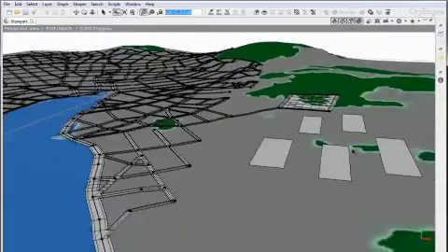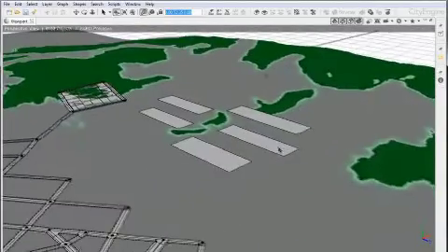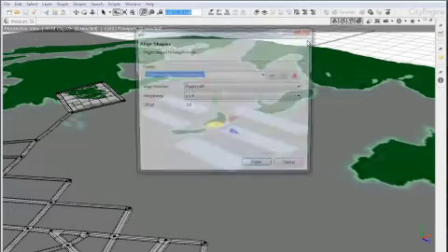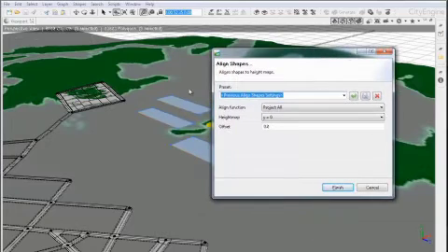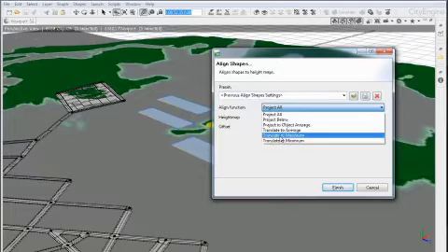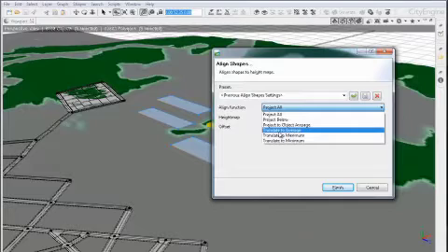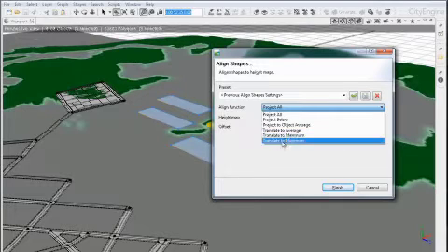So let's continue now with the static shapes here. Let me select these, and for those there's also a specific button here in the GUI. So let me use the Align Shapes to Terrain dialog. Now here there are multiple possibilities. On the one hand you can project, so that each point is individually projected down, or you can translate, and this basically moves the whole shape up or down, but it keeps it planar.